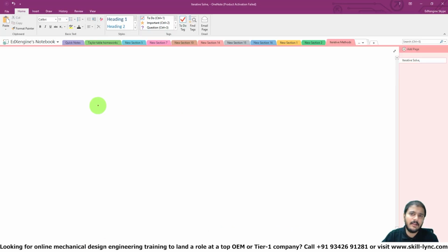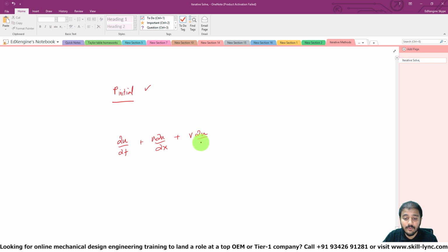That's basically it. So how does this all work together? Well, when you're setting up your CFD simulation, you set up the initial pressure, right? If you remember, under regions and initialization, there is an option to choose this. So you have chosen this. Now with this pressure, you evaluate your momentum equation, right? So your momentum equation is, you have your ∂u/∂t terms plus your convective terms. Again, I'm just writing this for 2 dimensions, equal to minus ∂p/∂x. And this is where the initial condition is going, plus mu times ∂²u/∂x² plus ∂²u/∂y², right?